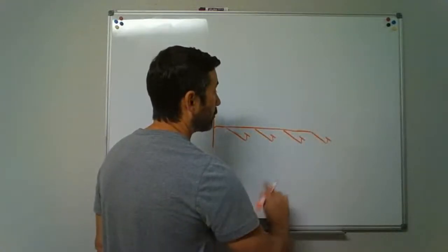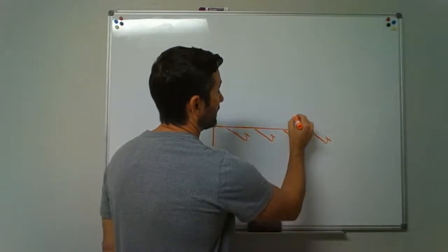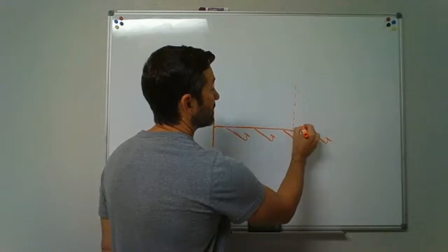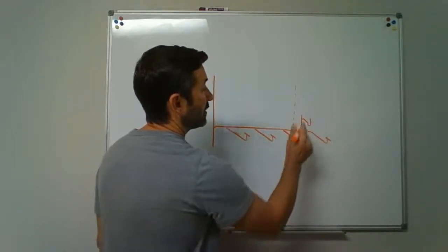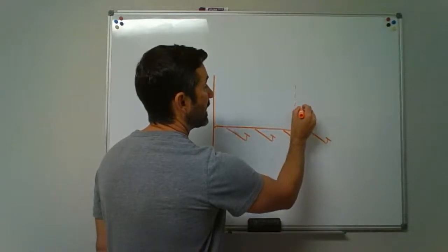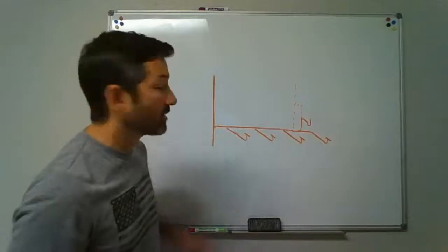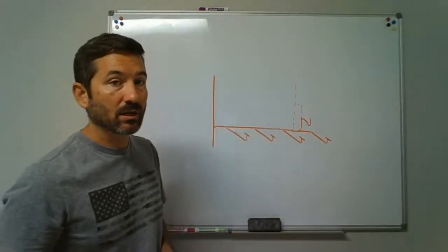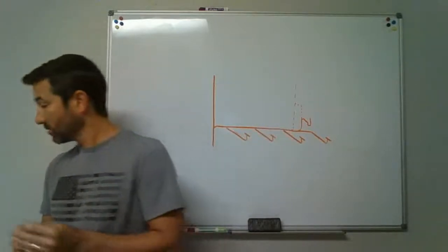But what we could do, though, if I'm going to say there's the circuit vent, I can come up and tie in and say, but I want a sink there. Okay, we'll tie it in and put a sink there. But now I could tie this vent to the circuit vent. But the circuit vent has to be its own vent tied in between. Okay, so we could do something like that. Would be permissible.